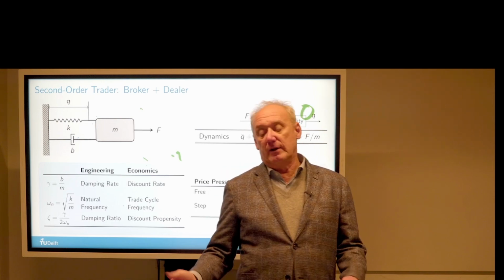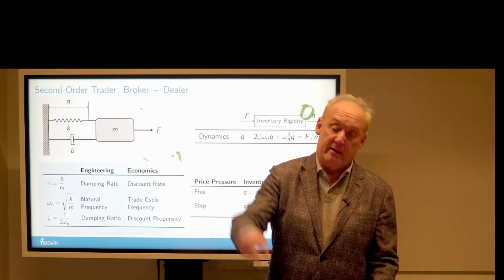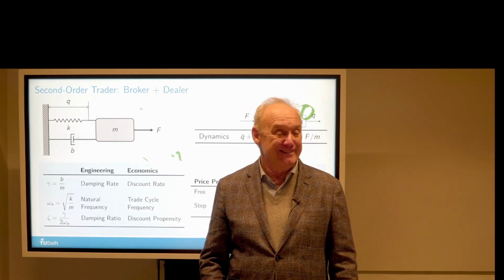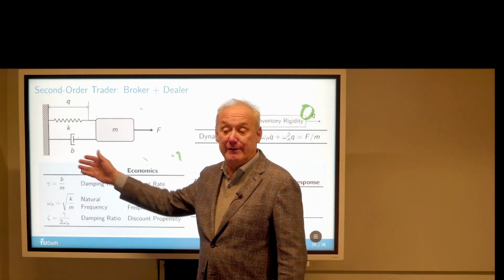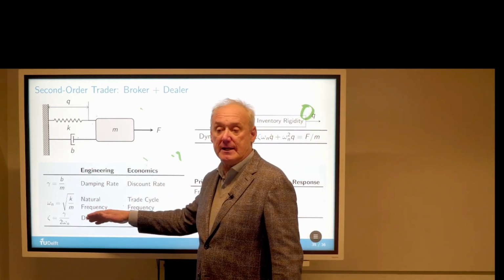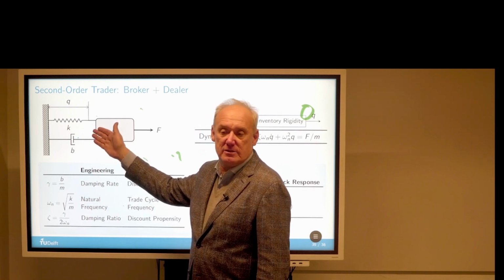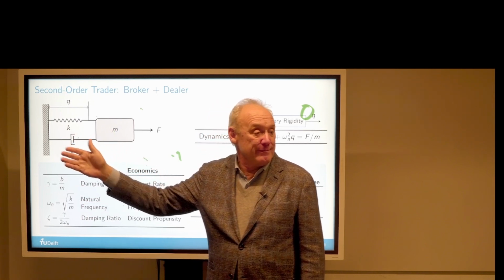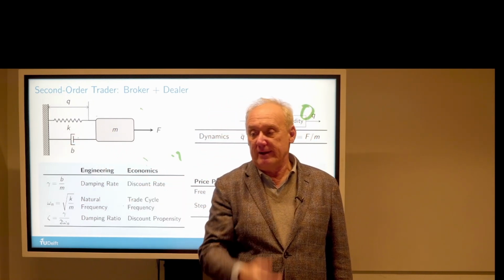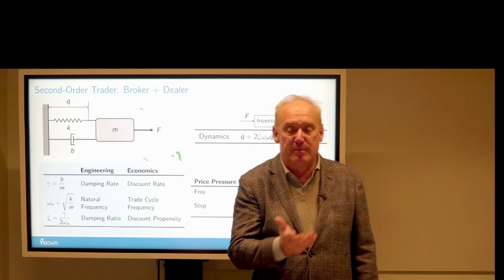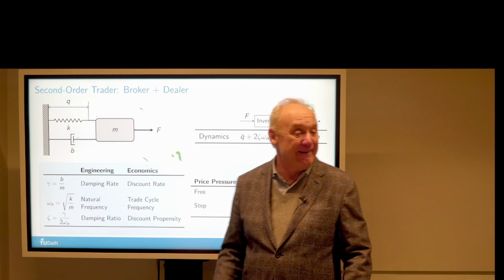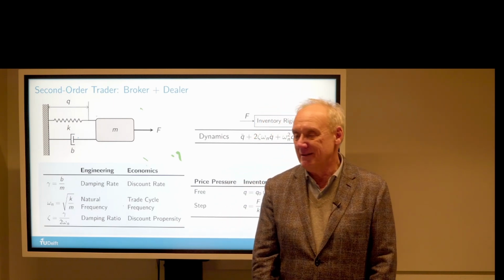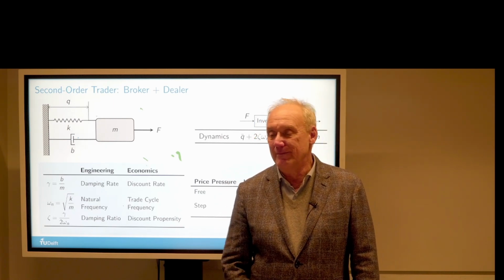Well, if you're an electrical engineer, you might put some generator in and look at the oscilloscope, what you get out, right? Now, what does that mean? That means you just identify where the poles are. I haven't done a Laplace analysis, but this thing is a one conjugate pole pair. So all you need to know is what that pole is in the complex plane. Now, the one complex number is two numbers, so there you are. That's all you'll do, boom.